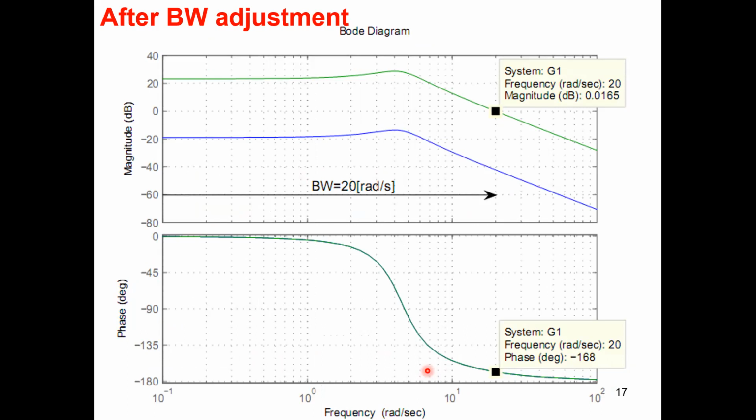So this is what we have right now. Now let me explain this again. When a sinusoidal signal of a certain frequency passes through a block, if it undergoes a 180-degree phase delay and keeps the unity gain, which means the same gain, you are in a very bad situation, because the moment you feed back that signal, you are actually doing positive feedback.